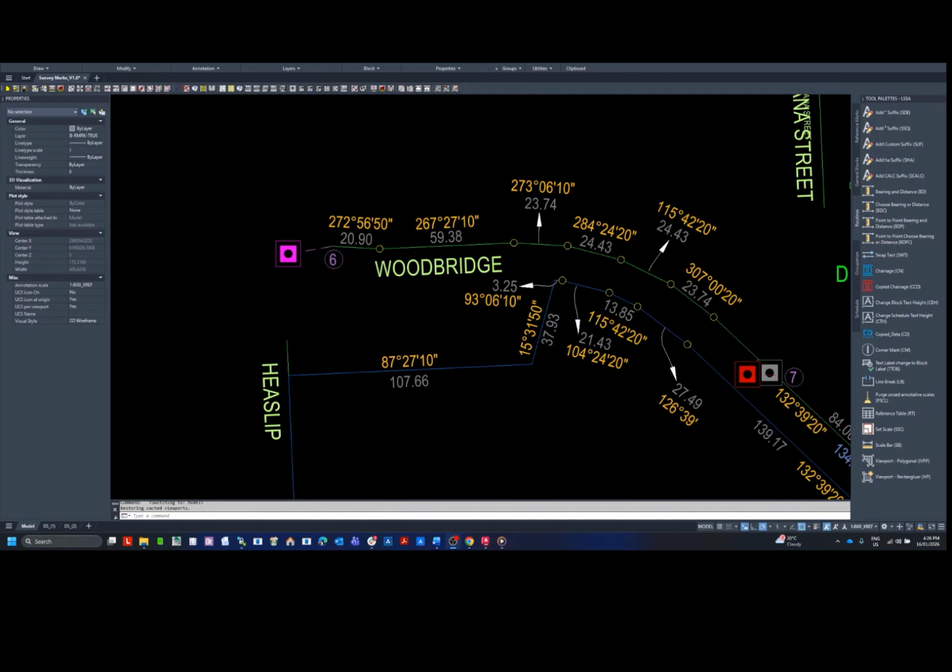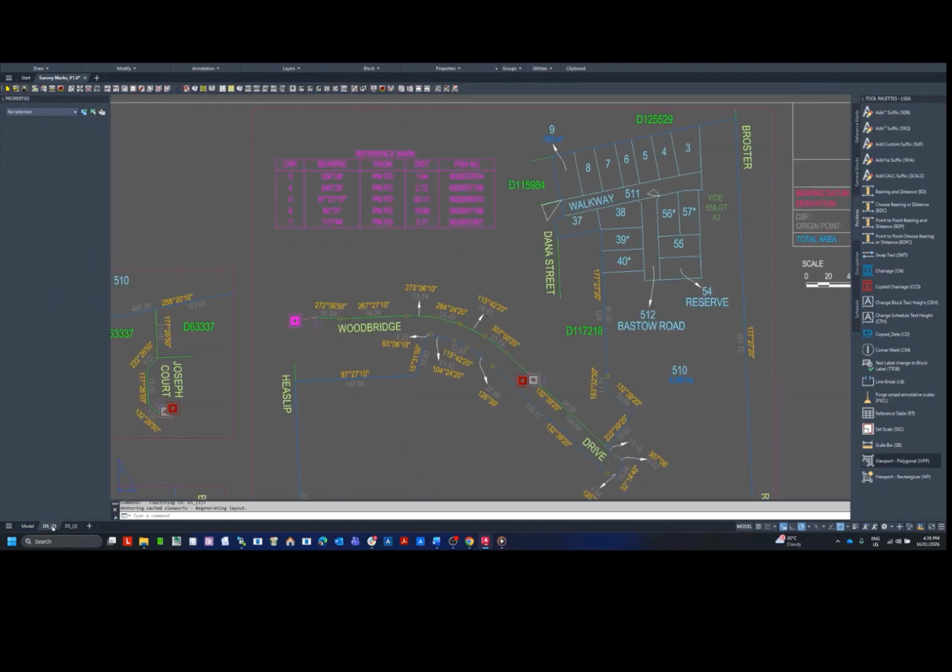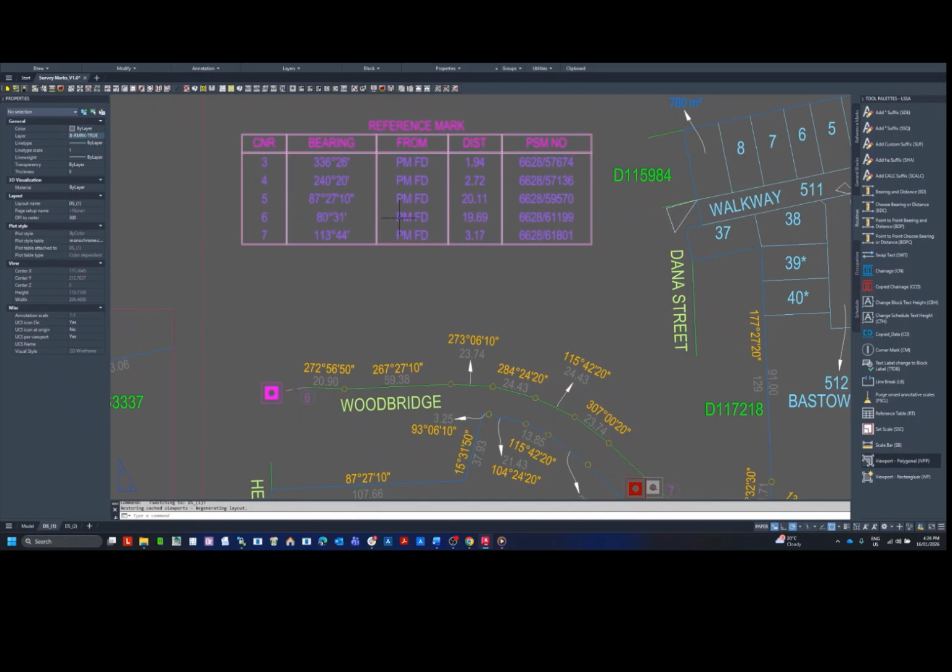The next drafting tip is in regards to survey marks. To reduce missing survey marks in the joins reports, ensure the connection line geometry matches the corner fixing details in the reference marks box. So this connection line here, we've got a length and an angle, and that should match our reference marks box with the bearing and the distance.